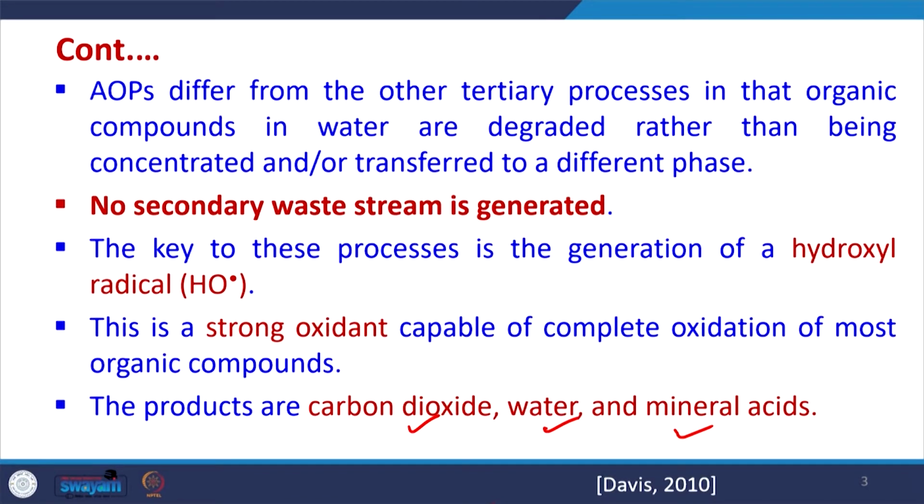For doing this, we use some other key things during the treatment itself. We always desire some key things in the treatment processes, and if those things get generated, we are able to remove or mineralize the undesirable products into carbon dioxide, water, etc. So, AOPs differ from other tertiary processes in that the organic compounds in the water are degraded rather than being concentrated or transferred.